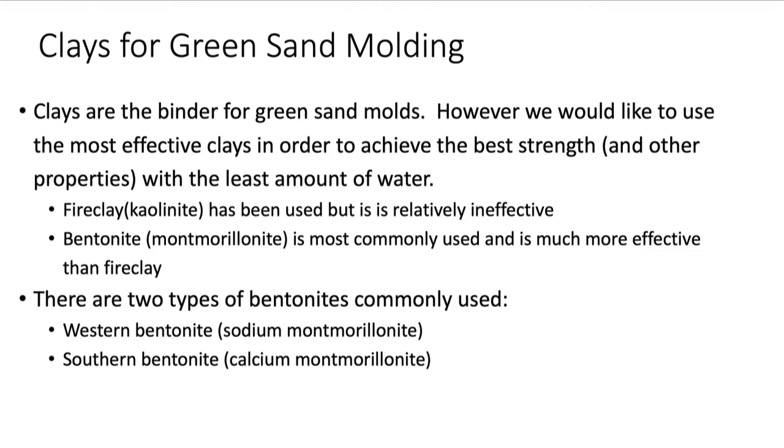Naturally, there were reserves of sand. It's called naturally bonded sand. We don't use it anymore because all the mines are shut down. But you could just dig up sand and clay. It was usually the fire clay type. It wasn't bentonite. So in the old days they called it naturally bonded sand. Then when they started mixing sand using bentonite clays, they would call that synthetic sand. But now pretty much all green sand is synthetic sand.